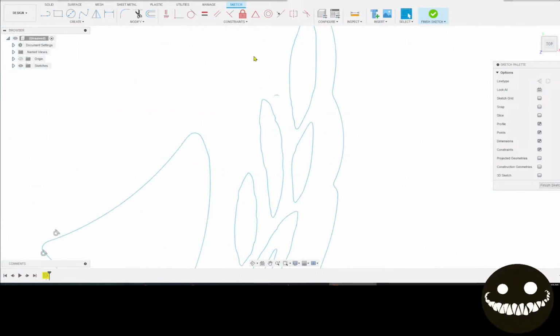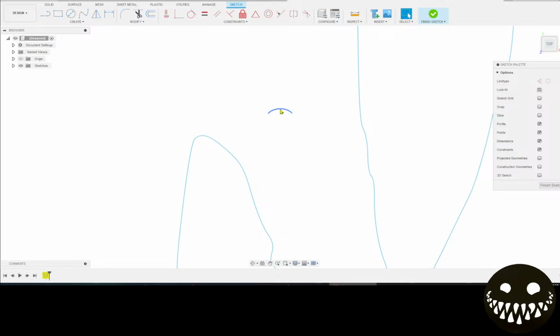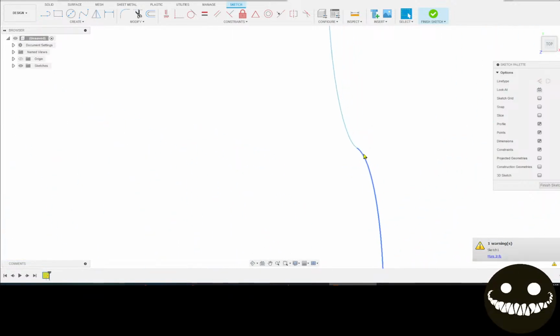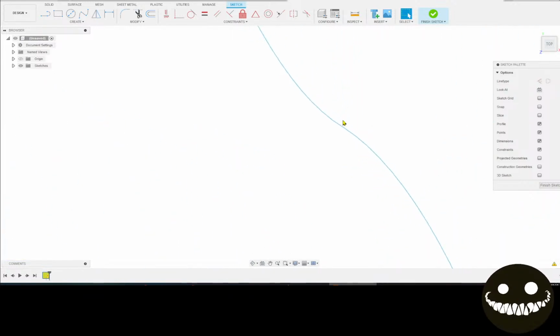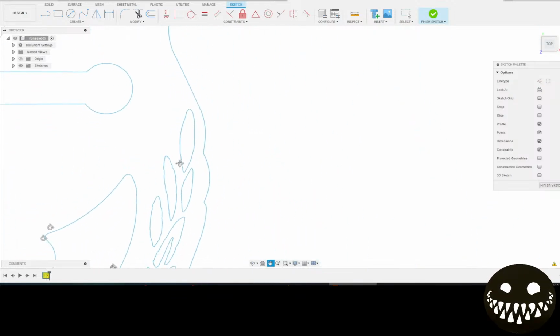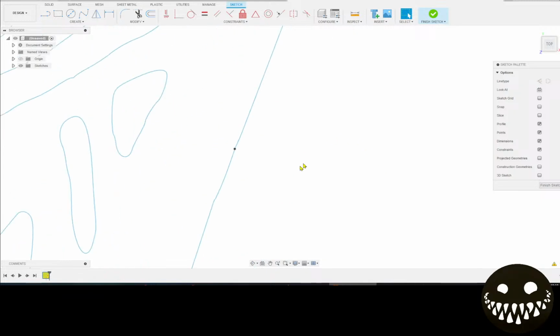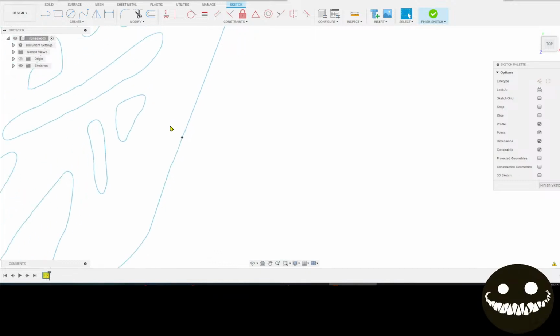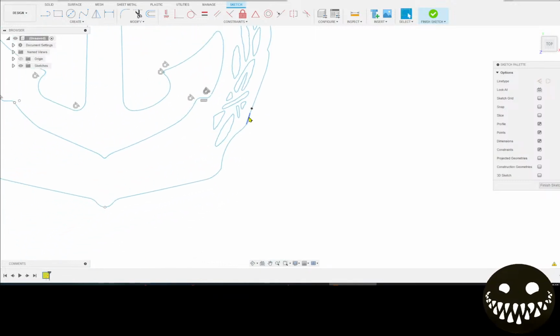And that's why there's a lot of these artifacts like this stray curve right here that's just out in middle of space. Or like, let's see if I can find one of these little janky points. But it's where these lines don't quite line up, and there's a little jog between them, just because the information from whatever produced this DXF just isn't translating perfectly over. So there's another constraint. You can see that come up as I hovered over. Looks like that was manually connected.